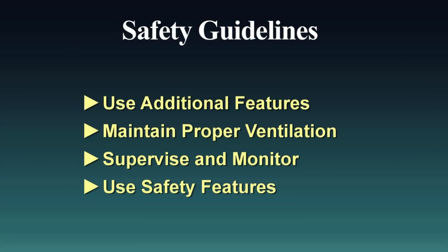Use safety features. Most electric room heaters come equipped with safety features such as tip-over switches and overheat protection. Tip-over switches automatically shut off the heater if it is accidentally knocked over, while the overheat protection prevents the unit from overheating. Familiarize ourselves with these safety features and rely on them to enhance safety.